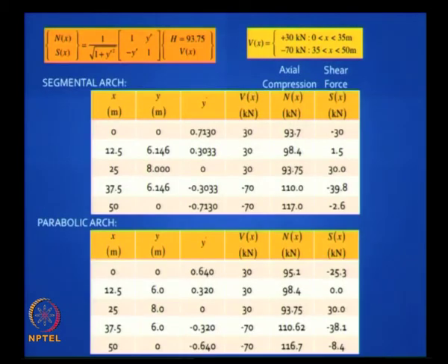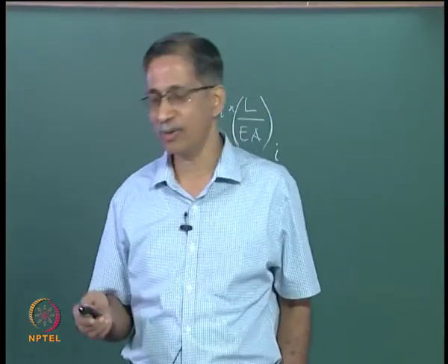They will look like this, and you can also calculate the axial force and the shear force once you have the shear force, based on the V and H, that is the vertical force and the horizontal thrust. So you will find that there is not too much difference between the segmental arch and the parabolic arch, because the shapes are more or less the same.